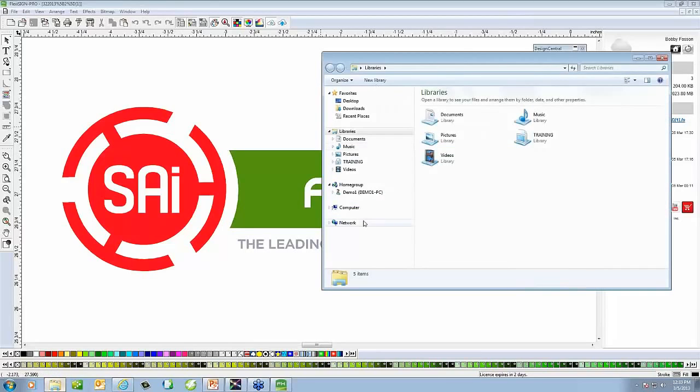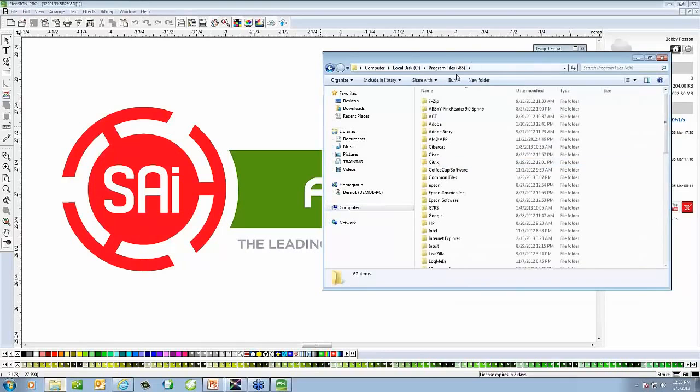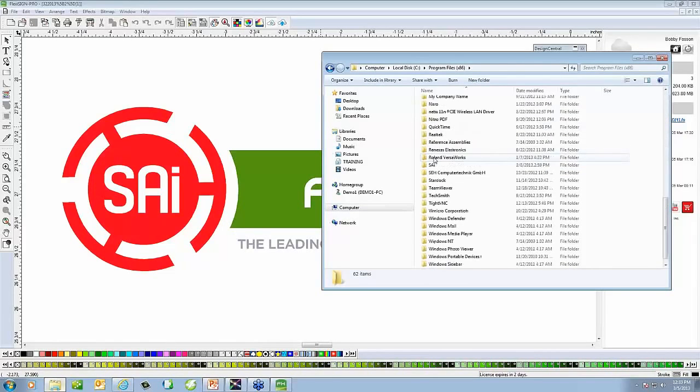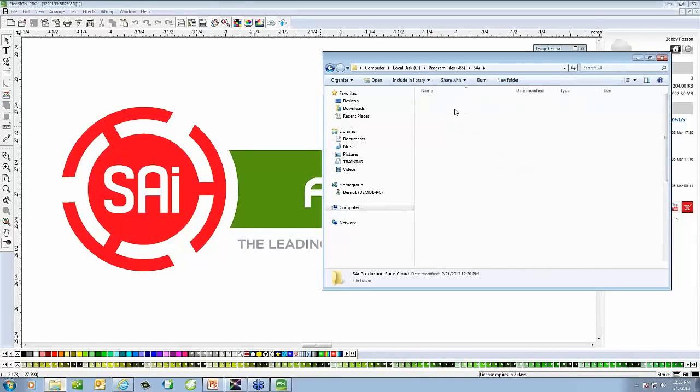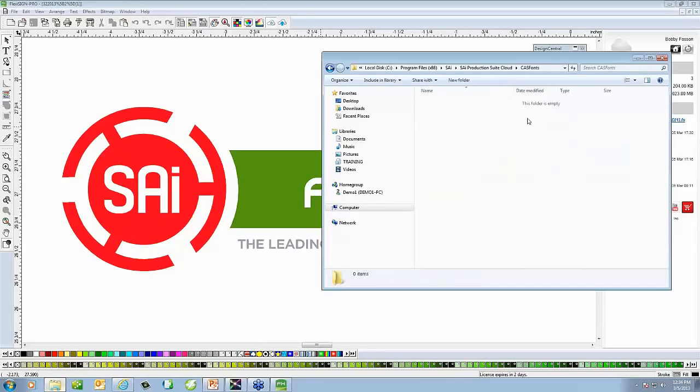So essentially, if you were to go into your program files, let's actually locate where I put it, you will have a fonts folder here. From there, or I'm sorry, the cast fonts. You can actually copy your cast fonts directories or libraries into here, reboot the system, reboot Flexi, and probably will have no problem getting those back up and going.